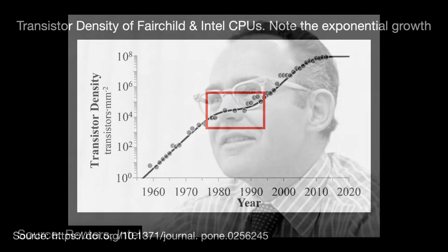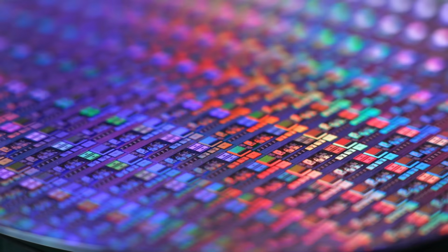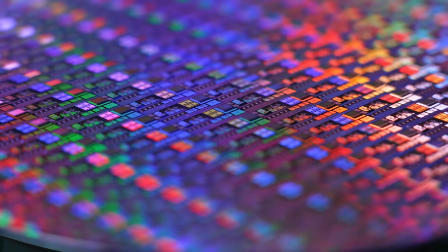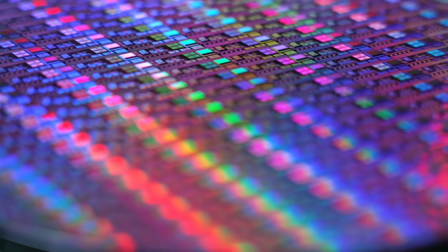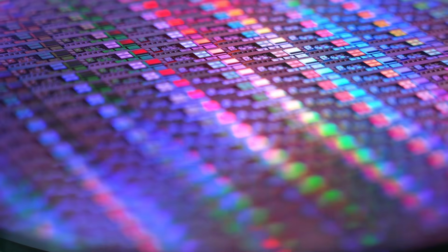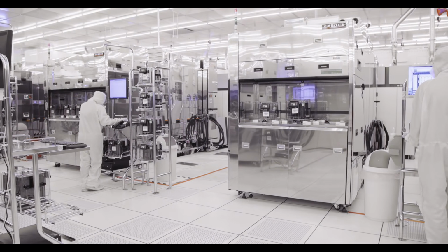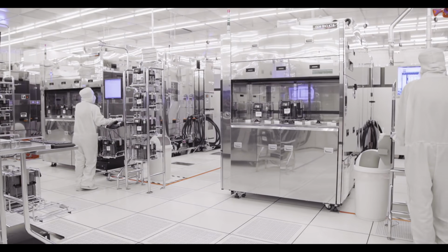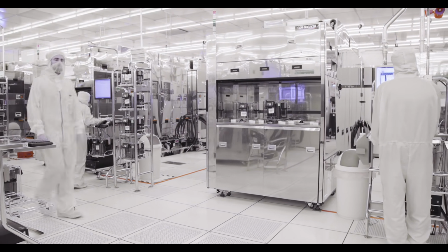In his 1975 speech, Moore cited 3 significant factors contributing to continued increasing complexity. The first one was to increase the size of the die. The second was called technical cleverness. In other words, using computer automation tools to lay out designs that can make better use of the chip die canvas. The third thing, and the one most relevant today, was the decreased line dimension, the depth, width, and density at which we can etch circuit designs onto silicon.